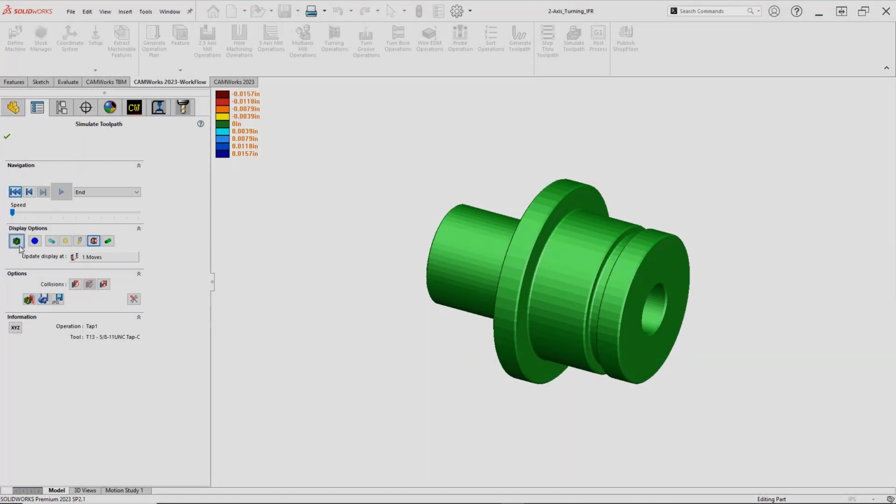The simulation shows a graphical comparison of the two items. The amount of deviation is identified by different colors on the simulated model. Any shade of the blue colors indicates presence of material. The color green indicates the part is machined to final size or net size. And any of the warm colors, yellow through red, means that overcutting is done on the part.